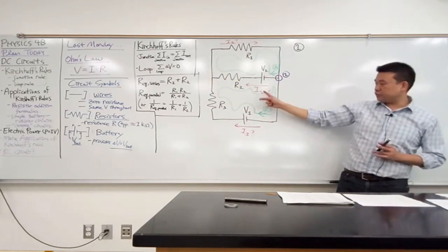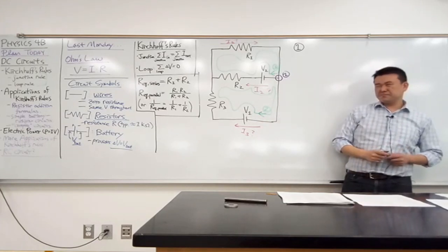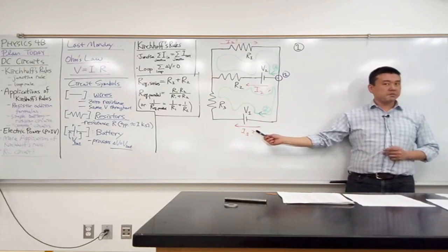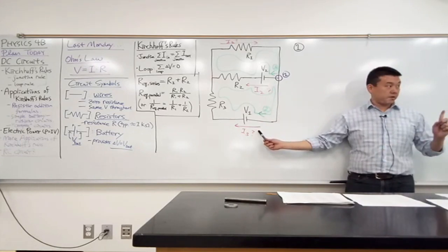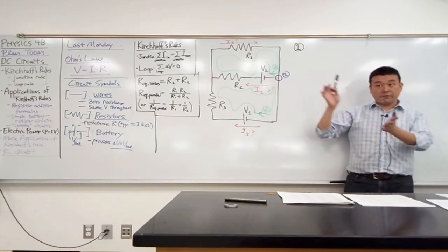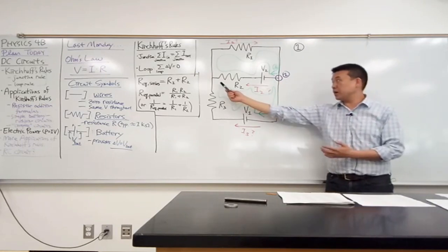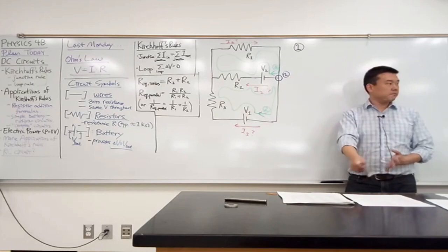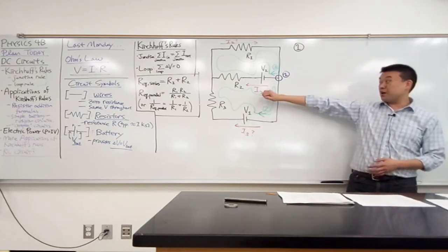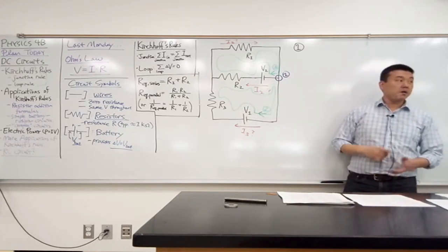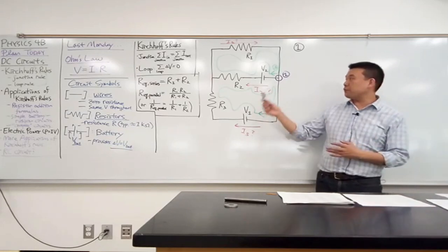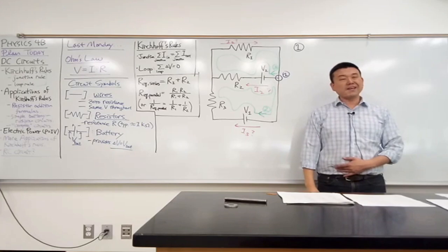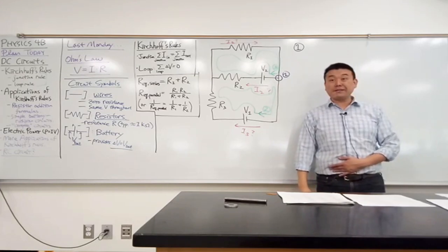With the currents I2 and I3, is it guaranteed to be this direction? There's a possibility that it might be different, right? You can imagine V2 being very, very small. In that case, I2 would actually flow this way. So this is the question I want to touch on and make sure you understand. So should I worry about that? Should I try to figure out what the actual direction of current is before deciding on one? Or can I label one direction and stick with it?